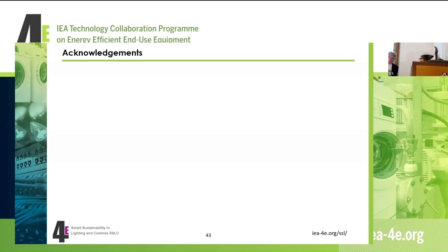When you saw the light coming up, the pulse effect, why does this pulse effect exist? What is the reason? It's the change in temperature of the chip from when the current first goes through.